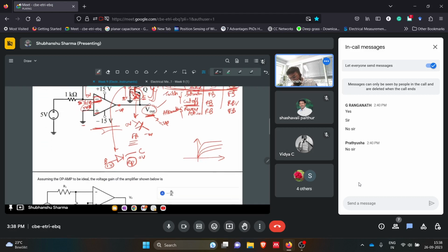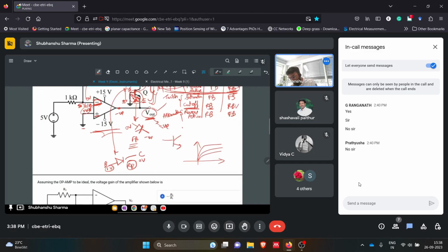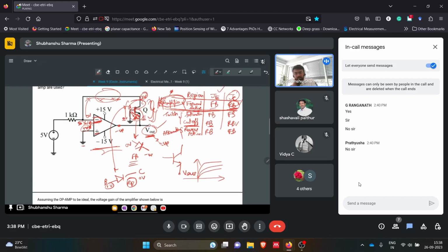Now this is acting as an amplifier. So if I make this circuit, this is V output. Once this feedback came into picture, and after all this operation, slowly the V out comes down to what? So this was ground, this is ground. Okay, so this was 0 volts, this is 0.7 volts. We know that it is acting as an amplifier, so there is a 0.7 volt drop here. So what will be V out? Simple, 0 minus 0.7 equals V out.